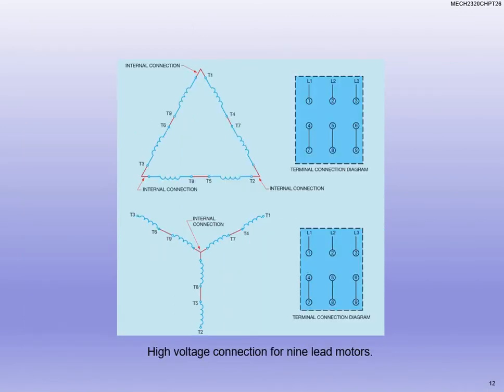You're going to get a terminal connection diagram when you get your motor, and you're going to be able to see which ones connect to the lines coming in and which ones terminate at the motor. You can see where L1, L2, L3 come in, and then 4 through 9 connect at the motor. Those connections are pre-wired internally for you to all the correct stator windings. You have to make sure that you make the correct connections here based on what the manufacturer says to do.